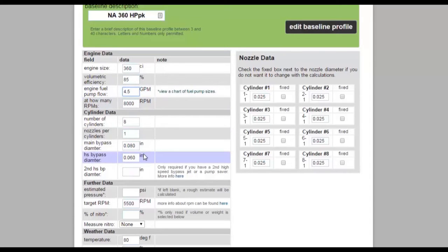The second one is a target RPM entry, and this would be, for example, the engine speed entry that you would want coming out of a turn in this particular course, such as a short course. This can be changed to higher or lower values to evaluate the lower operating range in different engine combinations. In this case, we have it set at 5,500 RPM.